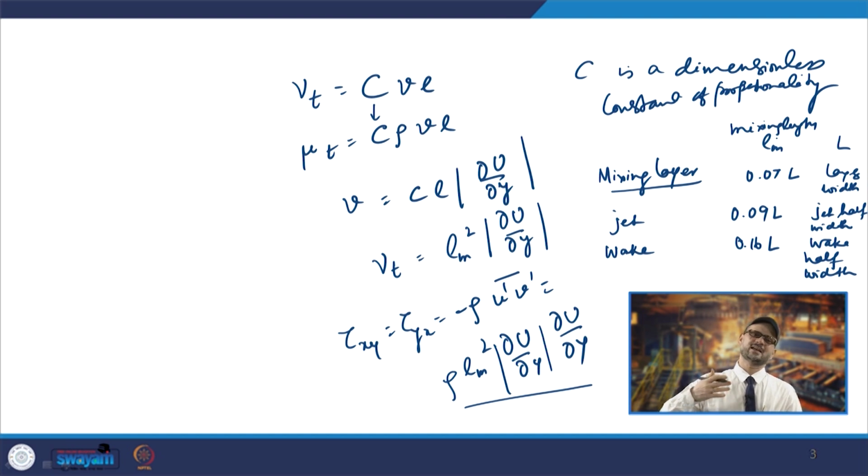They are used basically in the turbulence models when you are trying to predict these turbulent stresses. Its use will be there in the Tundish flow basically when we do the Tundish modeling. In that case, when we have to predict the quantities, which kind of model is to be selected. Being a simple model, it takes minimum time to solve. So, you can start with this model and then go to other models and see how they are predicting your different output parameters. So, this is about that.